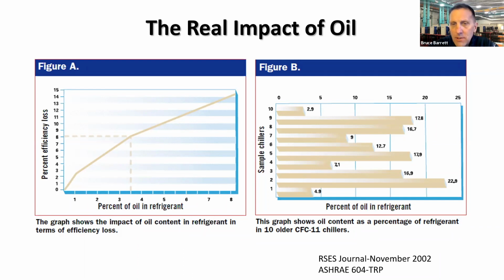So how does oil get into your system over time? Well, one, there's initial charge for oiled machines, and right off the bat, your chiller performance is going to be fine. But over time, that oil will stick to the striations on the outside of the tubes, which increase heat transfer, and plug those tubes. And that performance lessens over time. Your approach might go from 1.5 or 2 degrees to 4, 5, 6. And that's simple math. Again, it's the 2-to-1 impact from oil to refrigerant.